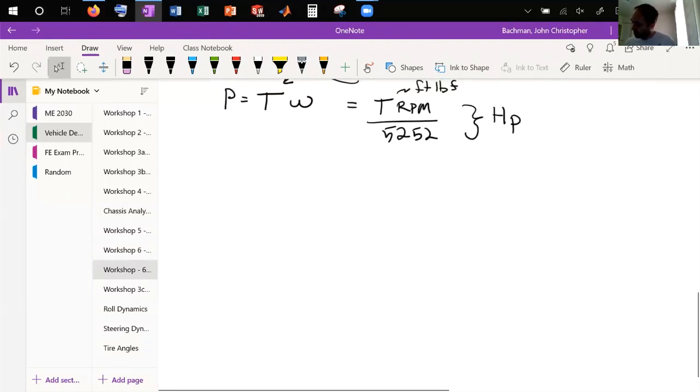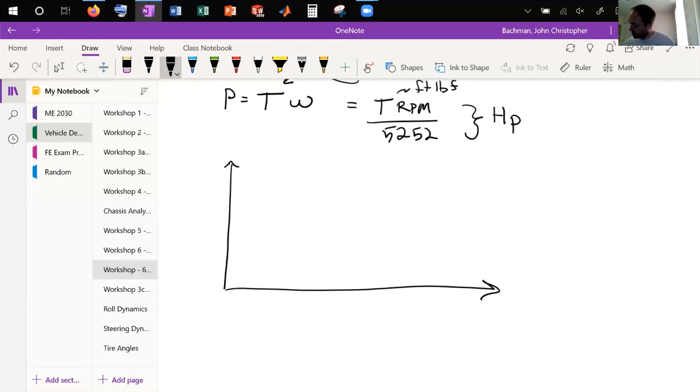So that's just some very basics about engines if you're looking at designing stuff associated with your engine. But usually with your drivetrain, you're not getting into as much of that. You're typically looking more at a torque versus RPM curve, right? You're looking at the output of your engine, usually between an idle RPM and what we might call the red line, where you don't want your engine to go over anymore.